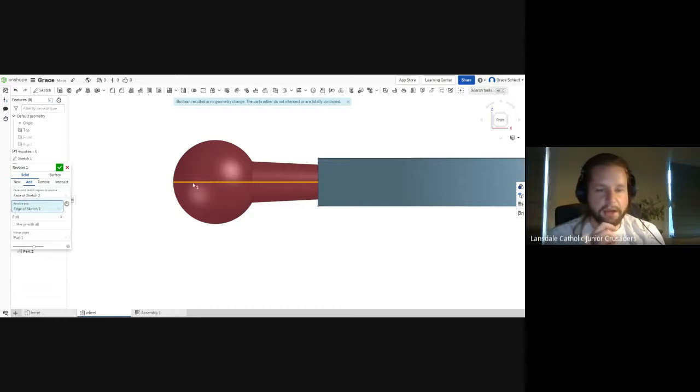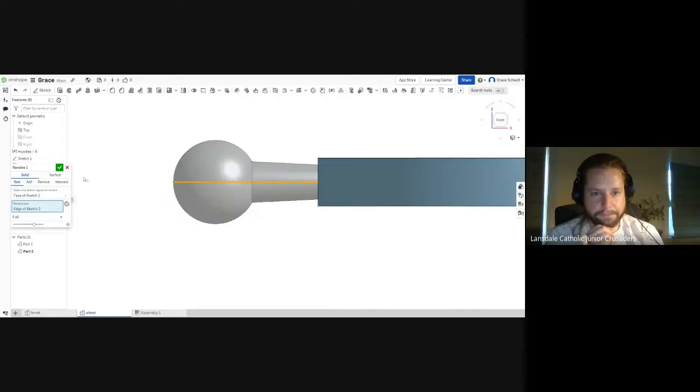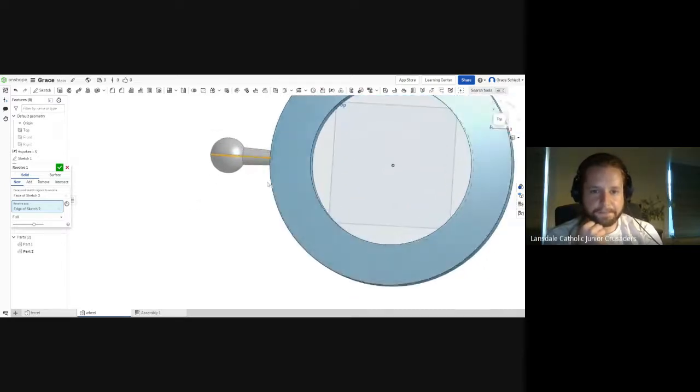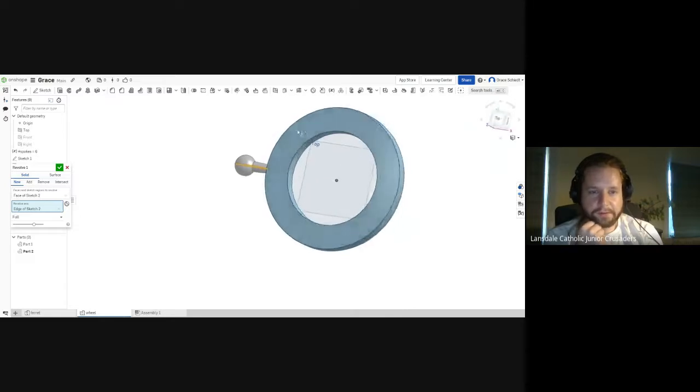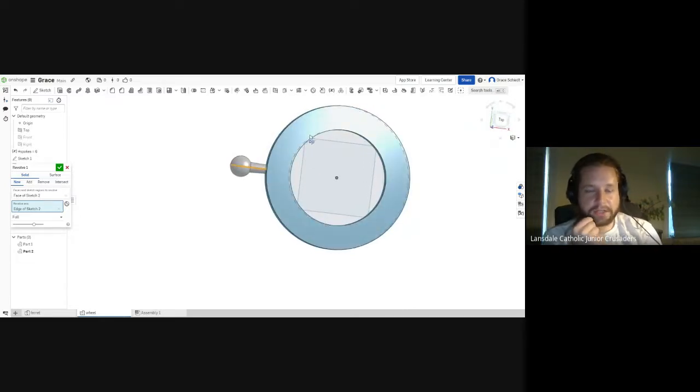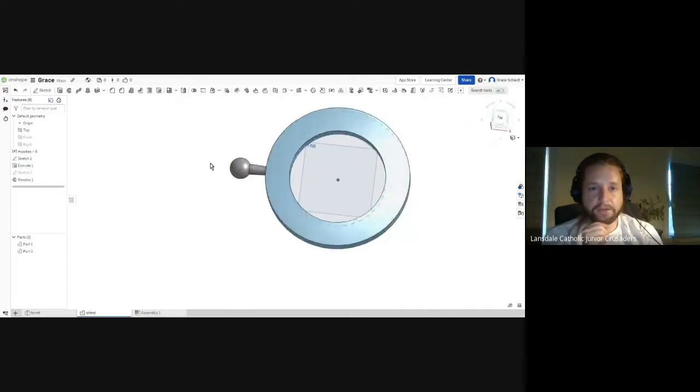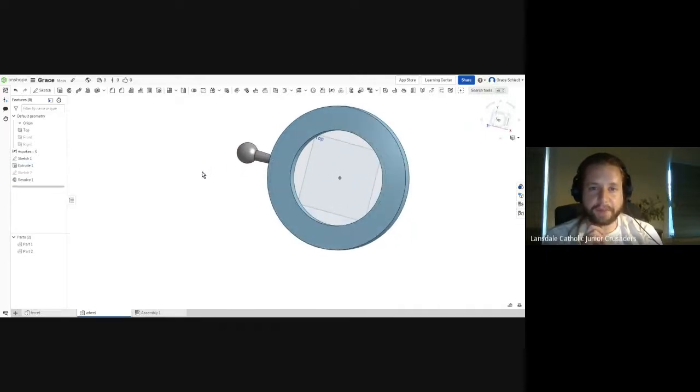And look at that. You want to do a new, by the way. So click new for now. We'll add it later. And rotate around, and you can now see your part. You can see your shape. That's pretty cool. Sweet. Click the checkbox on that. And then you can do a circular pattern if you wanted to, which the pattern key is right next to the mirror button up at the top.